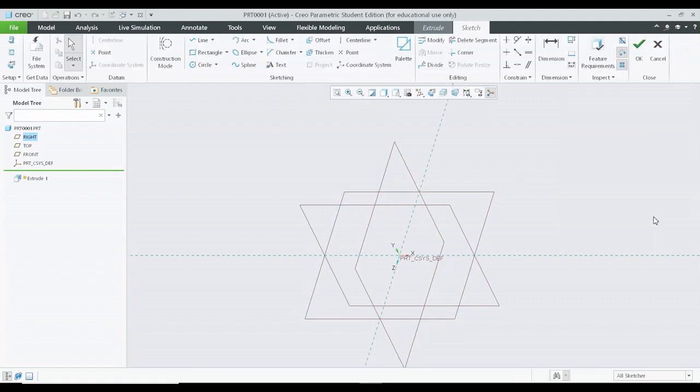Press sketch, and it is very important to align the view by clicking on sketch view. So what if I haven't clicked this sketch view option, and let me see what is the way you will be getting the circle. So you can see that the circle will be a little bit inclined.